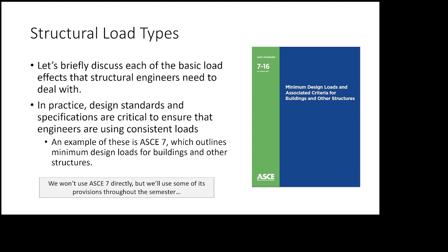It will tell you the wind speed that you need to utilize for a given location. You get my point? You shouldn't have to guess what is the snow load that I need to use to design a building in Albany, New York. Look it up. That's what these guides are for. They help engineers utilize a common standard for design of structures.